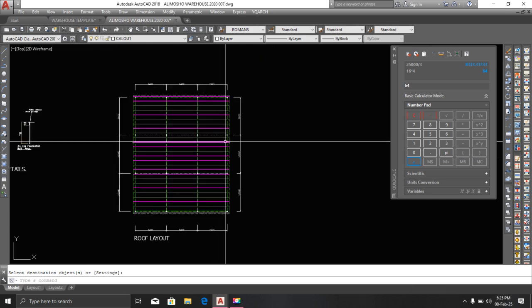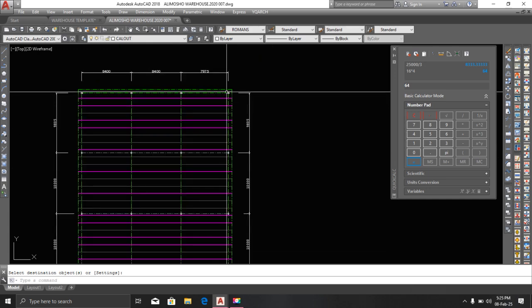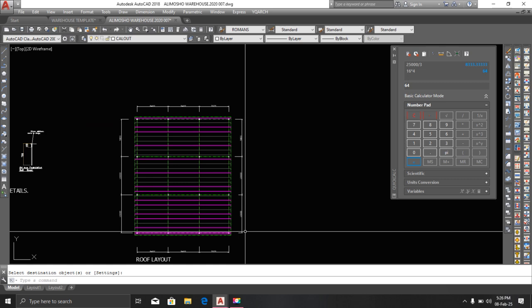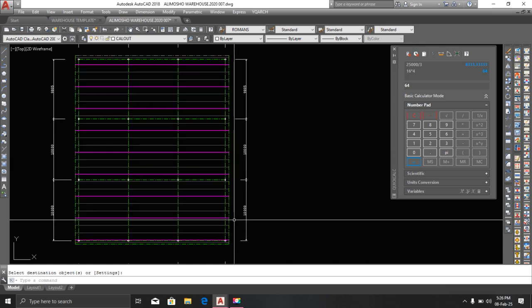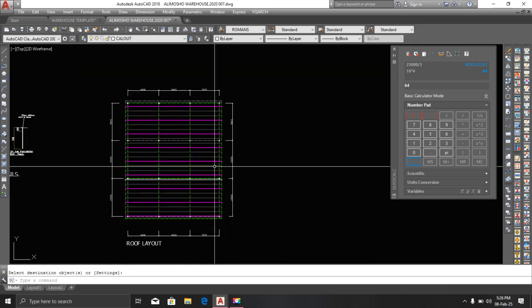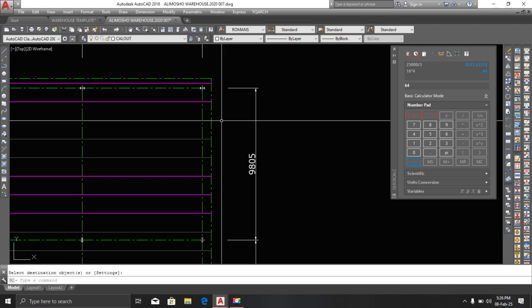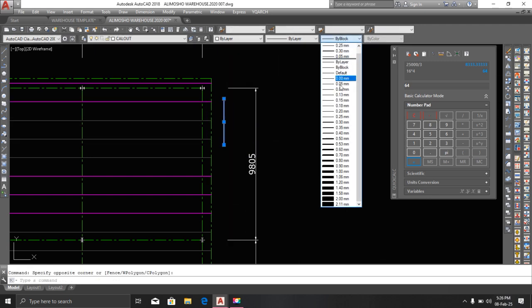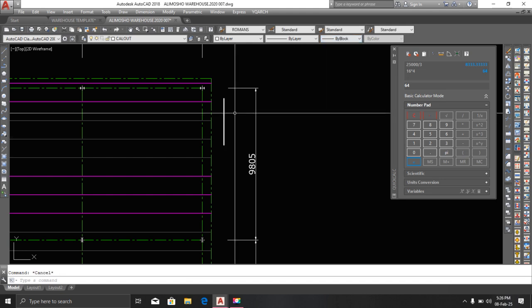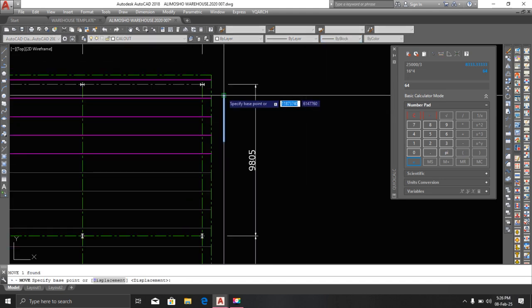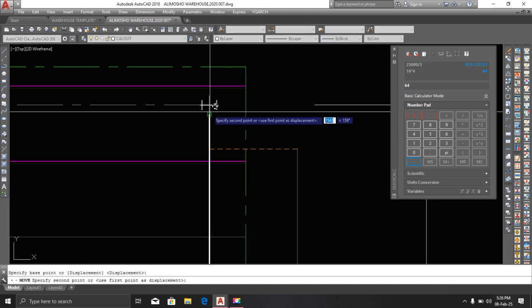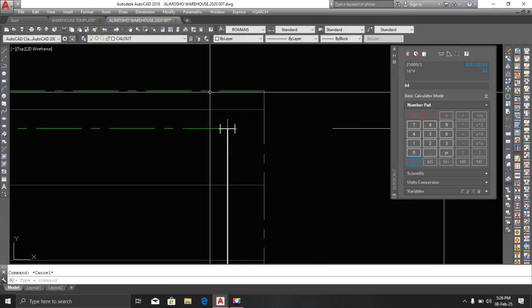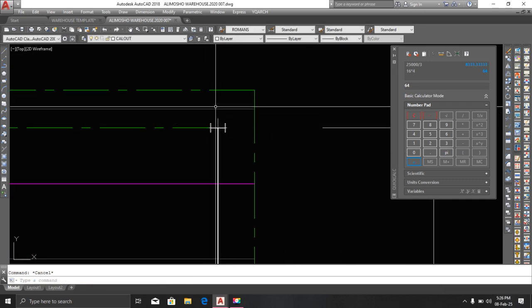So next thing is that let me have the rafters. So I want the rafters to be here, all the rafters since we are facing this direction. Let me have a thick line outside. This line, let me just increase the thickness to be 0.4. Let it be white. So I will have a rafter here, and this will actually be a canopy rafter.